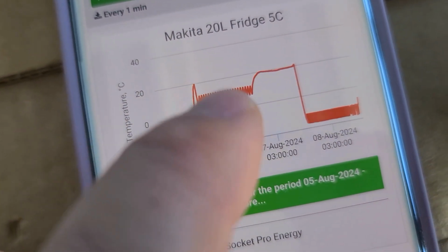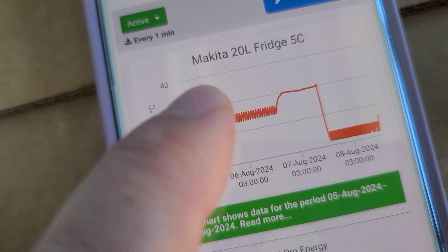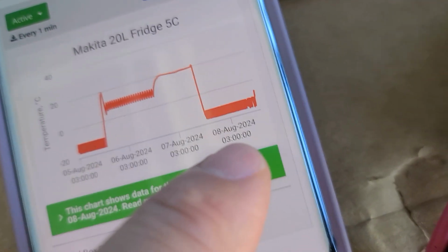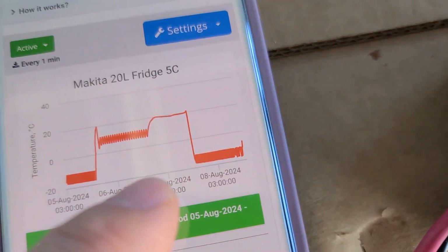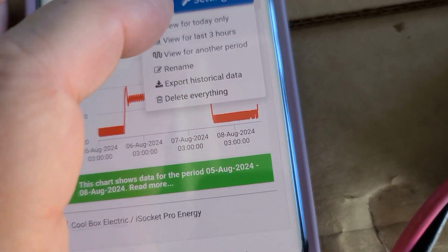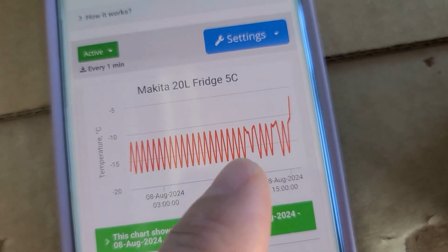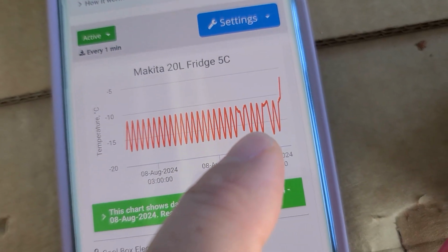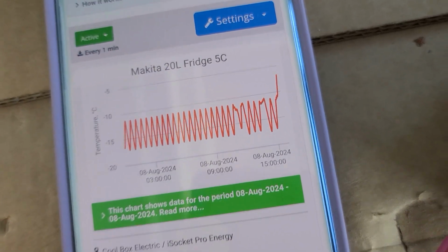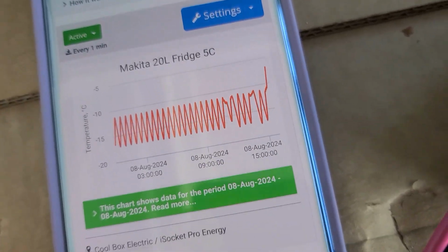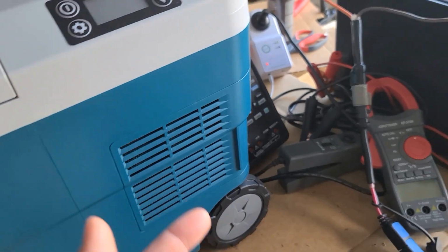So all nice profiles, yeah. So it's when we heat it. Then we put again for test for the freezer mode from the battery, and I see some issues. Here is the nice feature. Look, I see a broken profile. So it tells me that something is happening either with the compressor or with the power source.